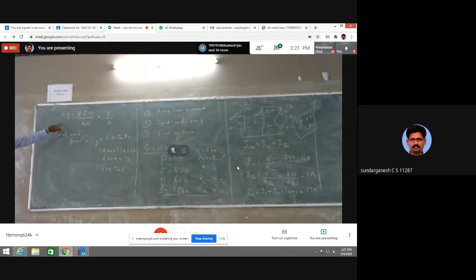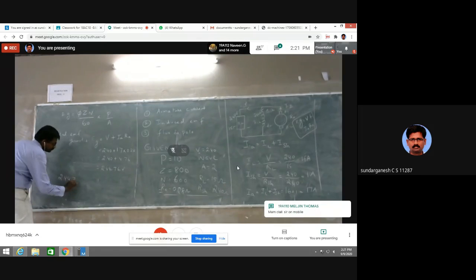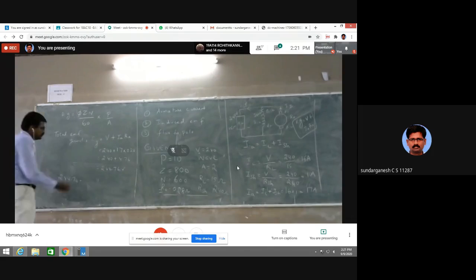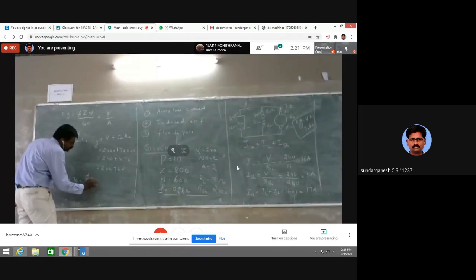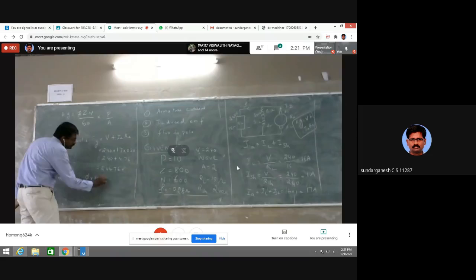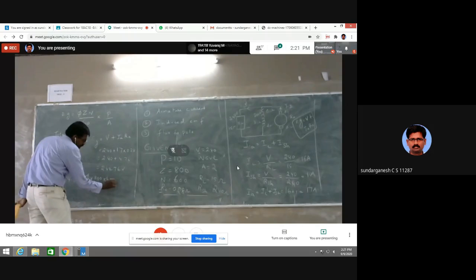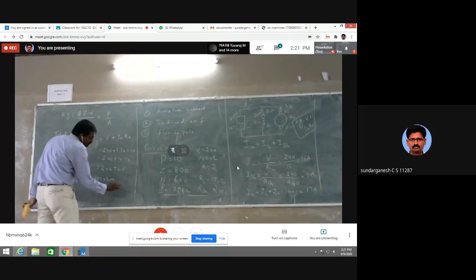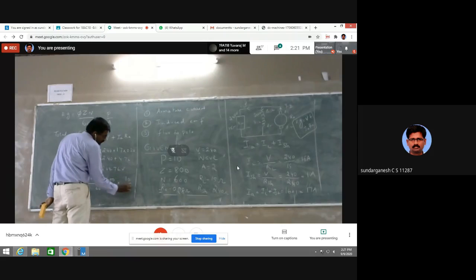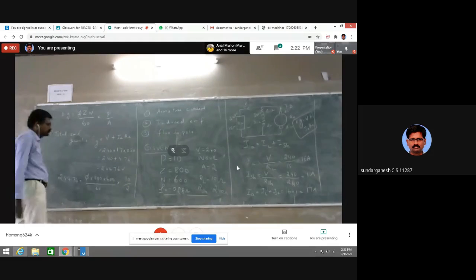Now I am using this formula to find phi. I know the generated EMF, 244.76. So phi into 800 N, 600 by 60, P is 10, A is 6.